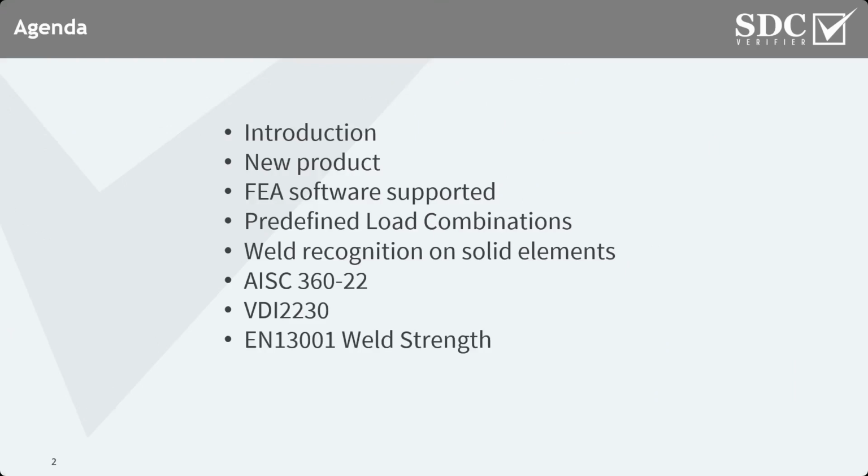We already have static strength and fatigue checks in our library, so now the weld strength is also added. Hotspot stress is now available in all fatigue-related standards, and Rainflow counting is also available not only as a separate tool as it was before, but also within the checks. It's important to notice that both hotspot stress and Rainflow counting are available in the enterprise version of the software.